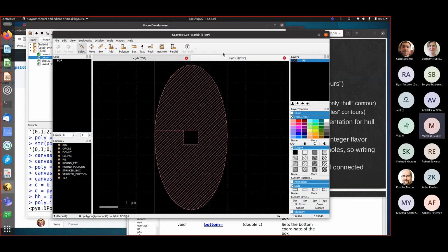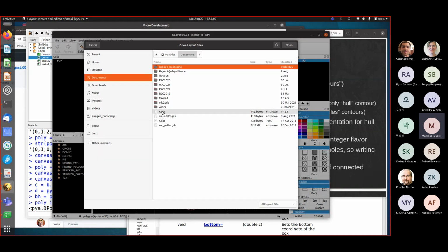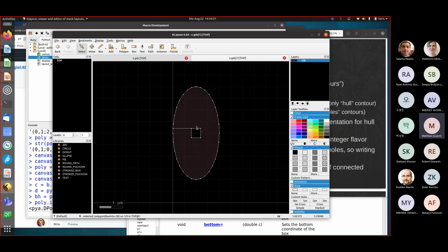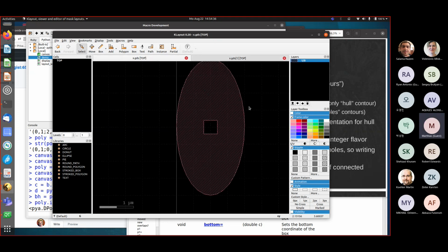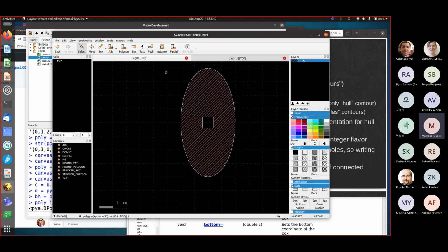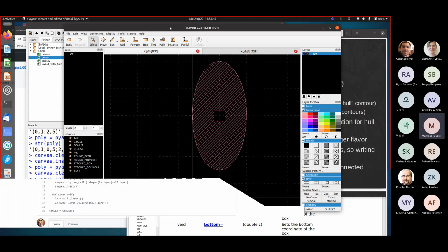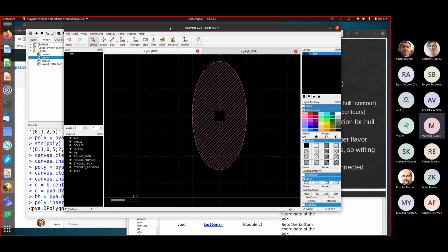And then I have reopened it by using file open, using the same GDS. And now you see what happened is this line was generated by KLayout, this connecting line. Because now this polygon is no longer one with holes, but it's one that goes like here, around here, goes into the hole, that way around, counterclockwise and back. And that's how such polygons are represented in GDS. If you do something like a guard ring, in GDS you would have to create something that has a connection line. If you code layout inside KLayout, when saving to GDS KLayout will do this for you. It will generate this connection line for you.